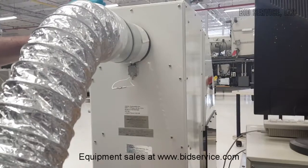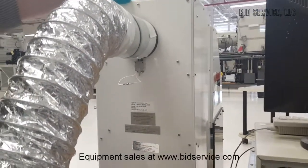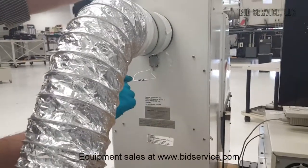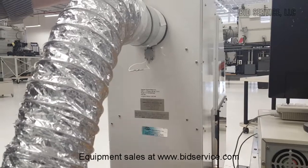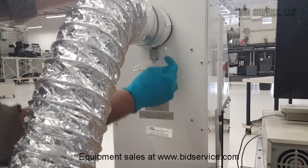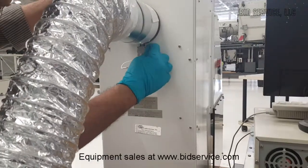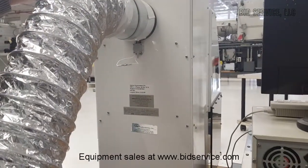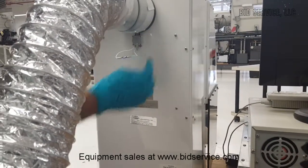When we connect this system, before even turning on the lamp, once you connect your exhaust, I will leave these two wires connected to the vacuum switch. For the lamp, you have to make sure that the two connections are on this side of the vacuum switch, and that there is continuity between the two pins here.